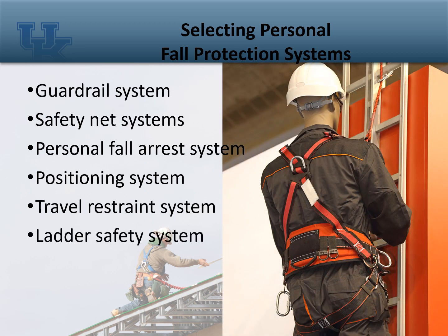The ladder safety system is a system attached to a fixed ladder designed to eliminate or reduce the possibility of a worker falling off the ladder. It usually consists of a carrier, safety sleeve, lanyard, connectors, and body harness. Cages and wells are not considered ladder safety systems.